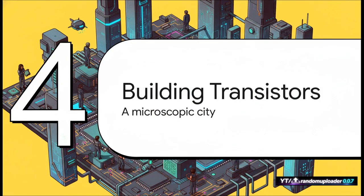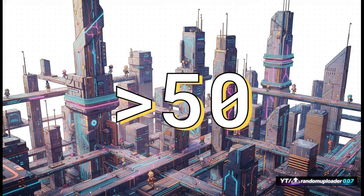But here's the thing. A CPU isn't just a flat drawing. It's a really complex, three-dimensional city of interconnected circuits. So what we just did, that was like laying down the first street. Now, we have to build the skyscrapers. And this is where the complexity just goes through the roof. That entire 5-step photolithography process we just talked about, it gets repeated more than 50 times.